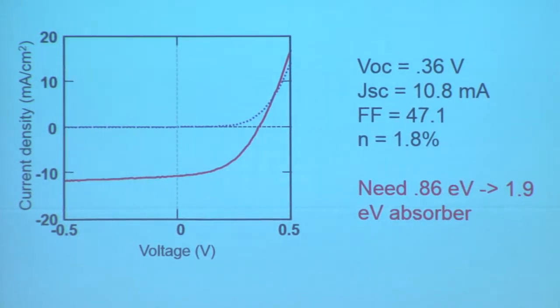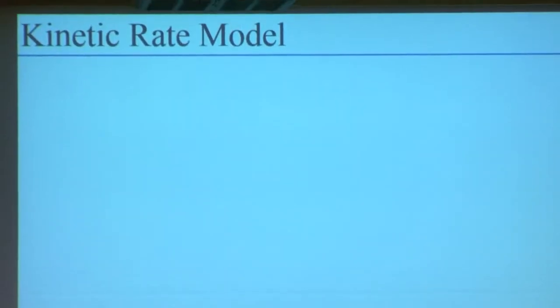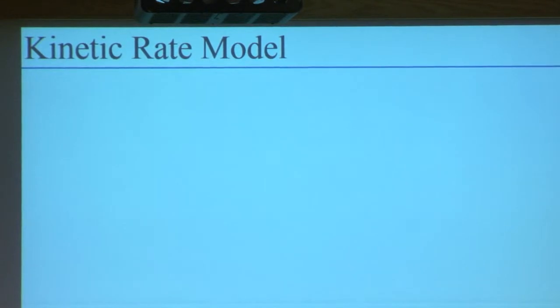So basically what we've done by doing singlet fission in this cell is we've doubled our photocurrent, but at the expense of our photovoltage, so we have no net gain in power efficiency. So we're going to have to find a way to make up for that absorption somehow in a future device design. And that's already been demonstrated by several groups, including ours. But we can examine what's going on in our device further by looking at the magnetic field